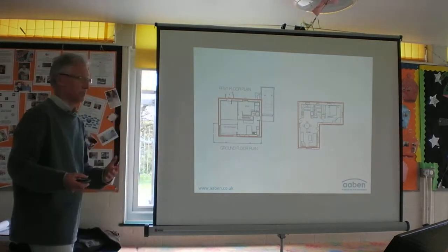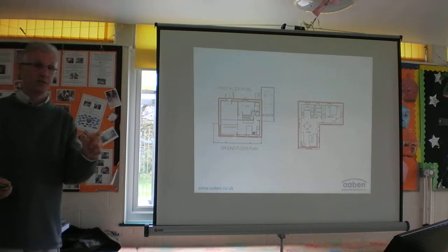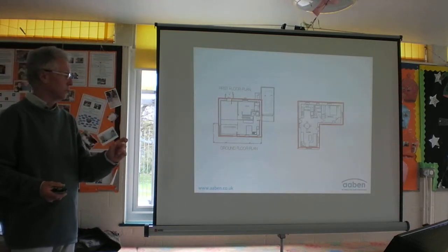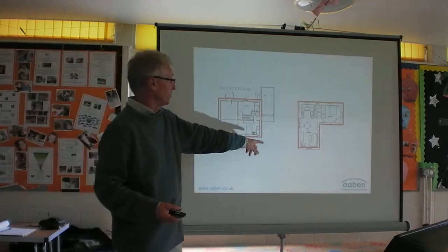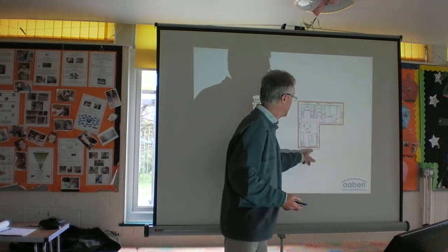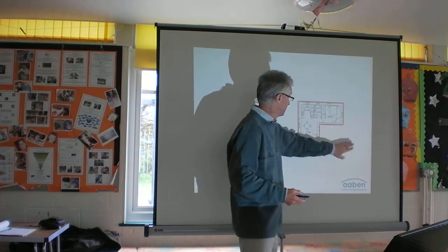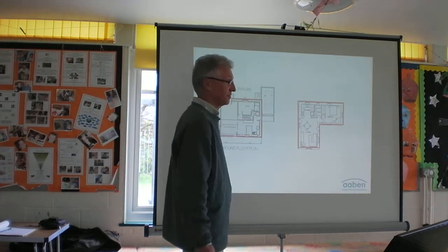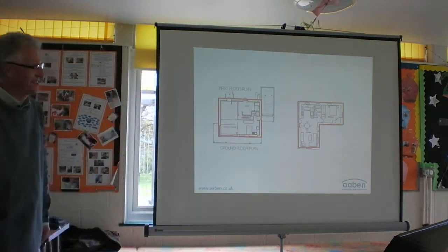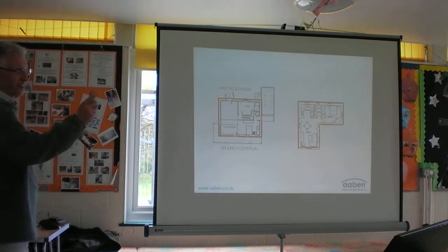You add 10% to the surface area of a building, you need another 20 mil of insulation roughly. And that one I think has got about a 25% increase in surface area. If you'd squared it off, you would have got an extra quarter floor space for the same amount of fabric just flipped over there. But you might get a really nice terrace outside your house where you can sit in the sun, and there's always a conversation.